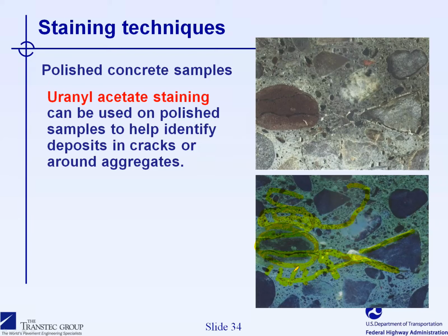So the presence of the lightweight aggregate particle may not be considered much of a safety area for the gel to relieve expansive pressure, because the gel will not necessarily reach those particles, but will be concentrated in the cracks per se. So I would doubt that the presence of those lightweight aggregate particles, which have a high porosity, will really be considered a preventive action against ASR expansion.